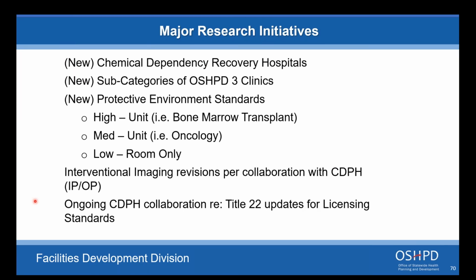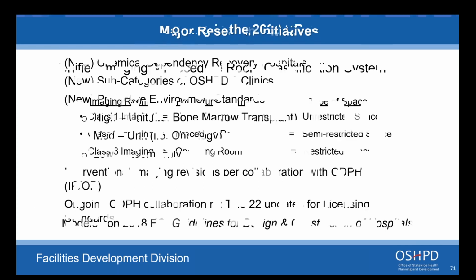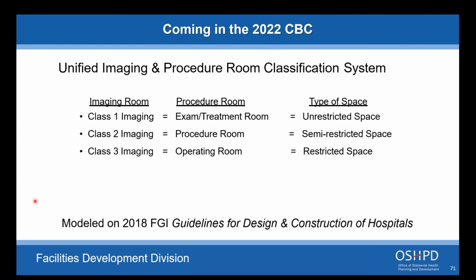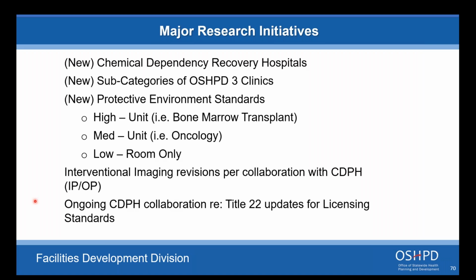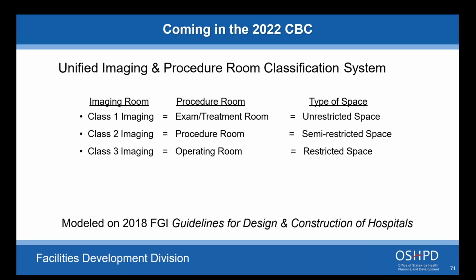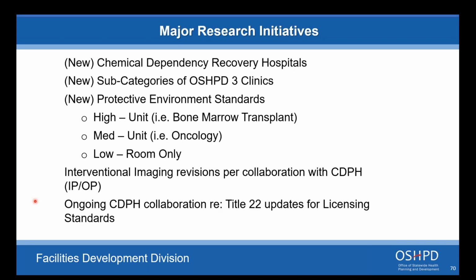We are currently working with them to try to clarify what's going to be required, when it's going to be required, who it's going to affect. Our building code states 6 hours for skilled nursing facilities, but they're referring back to NFPA 110. The 2010 version does require 96 hours worth of fuel, and this is an ongoing discussion, so we'll keep you informed on that and what's happening with that.